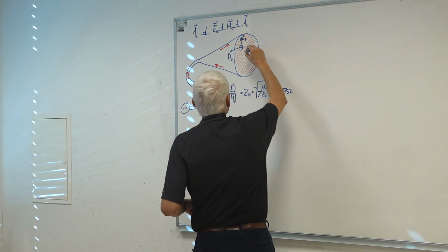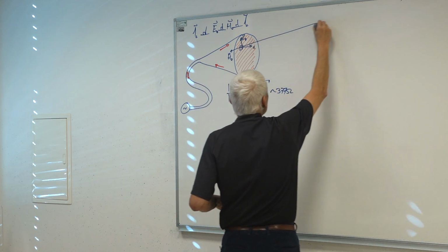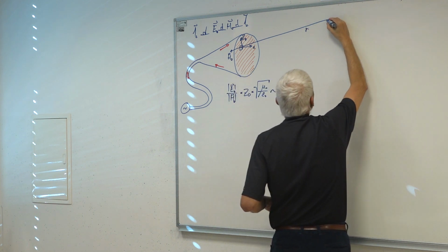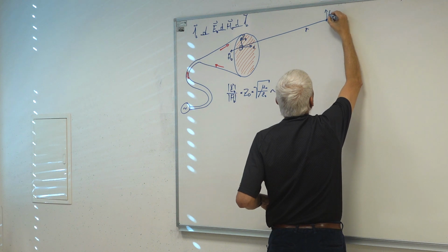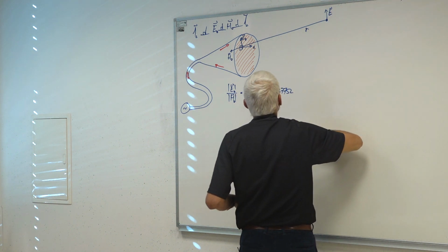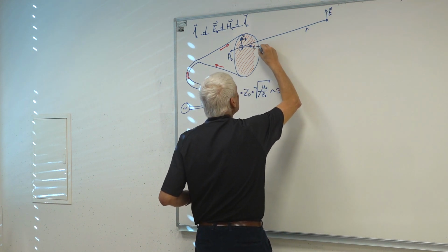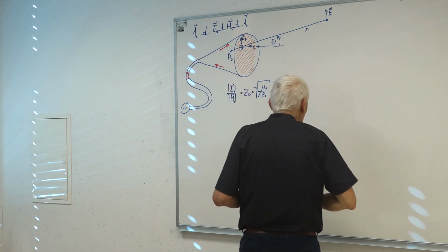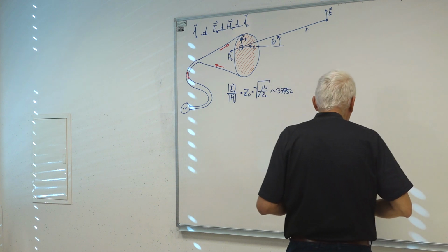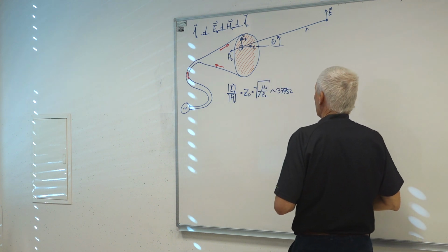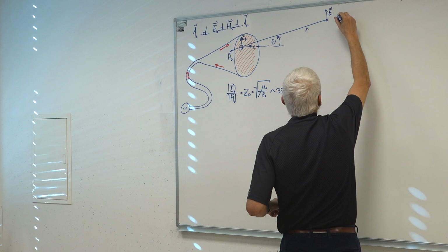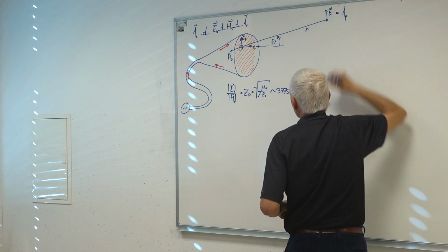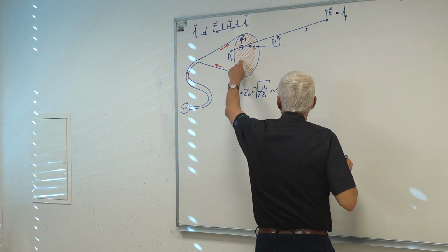If we try to calculate it in the far field, at the distance r, the field here, E, what is this field like? And this angle here is theta, the polar angle. We found out that this radiated field from such a Huygens source is equal to what? It has a polarization that tracks the polarization on the aperture.